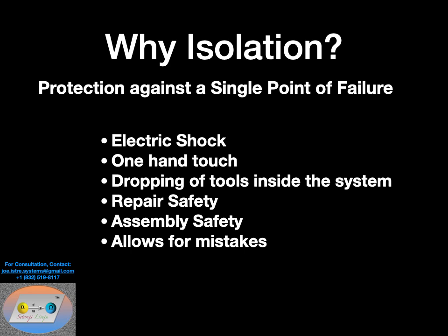You got to do some sort of connection from the module terminals to bus bars. So it has to be assembled in some way. So guys are going to be interacting with these bus bars and with the battery terminals. And we got to make sure that we reduce the chances of shock as low as possible. And isolation requirements and isolation design provides for this.